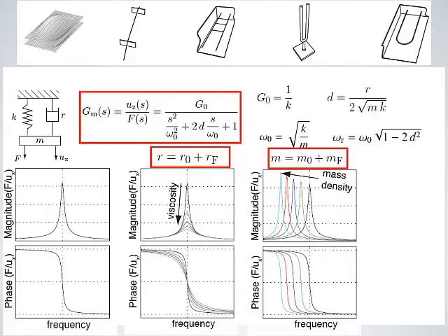All these devices can be described in common by a lumped element oscillator, which is exposed to the sample liquid. Put simply, if you record the frequency response of the resonator, higher viscosities yield higher damping, whereas higher mass densities yield lower resonance frequencies.